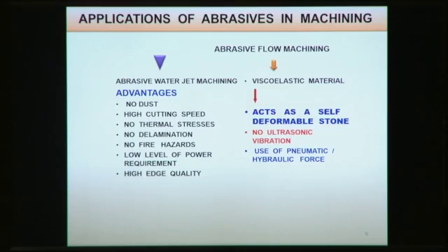So no thermal stresses, because abrasive particles hit the workpiece surface. So heat generation is very less. Unlike conventional machining processes, here the tool does not touch the workpiece surface. So heat generation is less. Also, whatever heat is generated is taken away by the abrasive water jet.